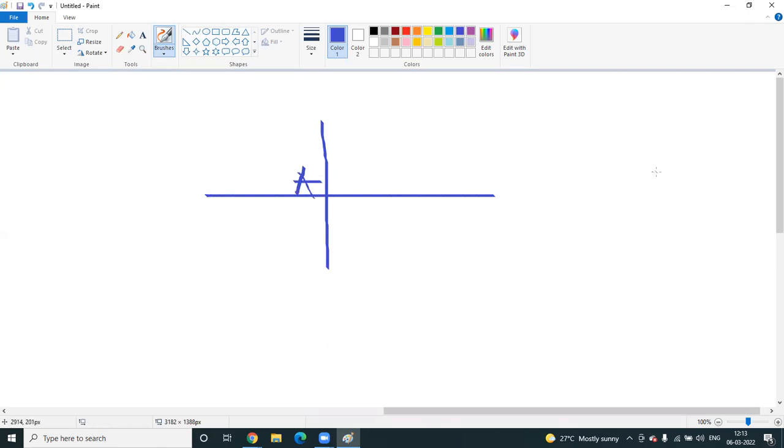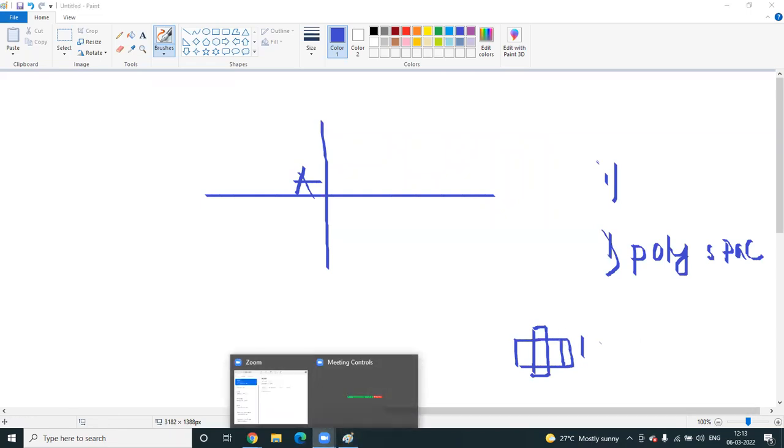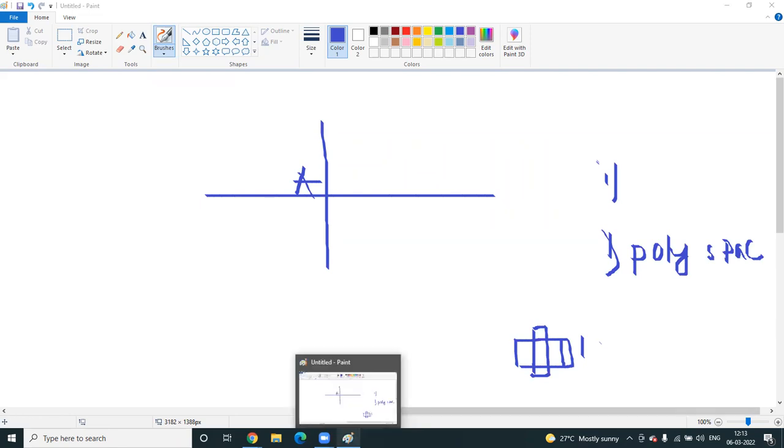And the two points matching are for not only the first point, but also the second point. When you do layout, the poly pitch, poly to poly spacing, remains the same. So don't do one device sharing, and even if one device you do share, the other drain is not shared. So what will happen? The poly sharing is not done. You can see the example in the layout also. So poly to poly distance remains the same. These are the two main factors required for matching.